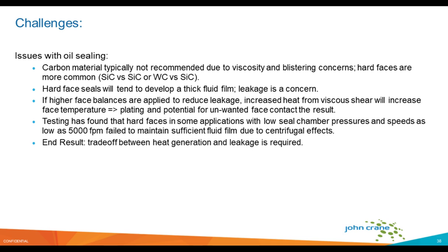In addition, John Crane has done a lot of in-house testing on hard faces at high speeds, and you really need to be cognizant of the centrifugal effects as you go to higher and higher speeds. The centrifugal effects eject that oil further away from the seal faces. So you need to ensure that you have enough differential pressure at the seal faces to create a fluid film for lubrication, but at all times we want to manage leakage expectations to within required parameters.